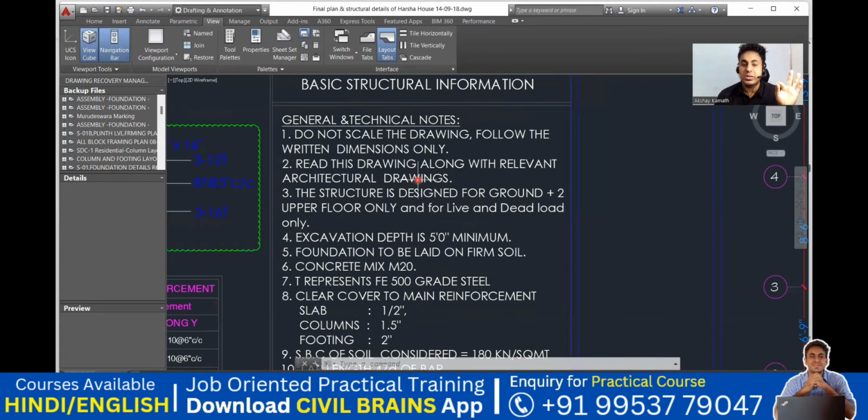That is strictly what they have written here. And it is only designed for live and dead load. Dead load in the sense the self weight of the beam, the column and all. And the live load is like once we get into that house, we all are live load, the furnitures and all. Along with that, we'll be having an earthquake load and a wind load and all. For that, this particular building is not designed.